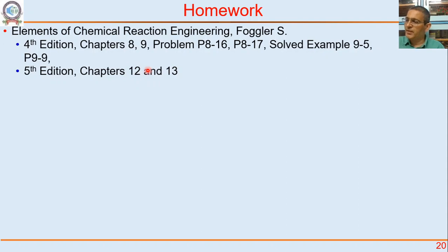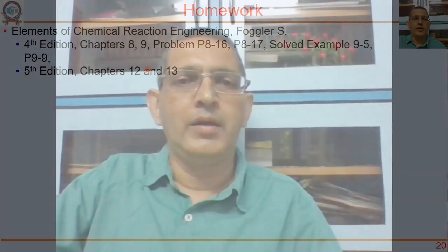So these are the considerations that go into a real life well mixed reactor. And you thought a well mixed reactor is so easy to understand. It has all these complications because there is an interplay between heat generation and heat removal, and it can lead to very complex behavior: multiple steady states, stable steady state, unstable steady state, dynamic behavior.